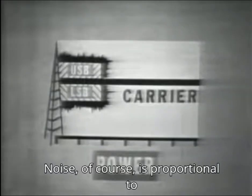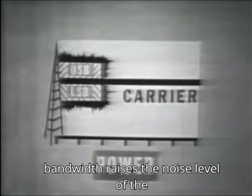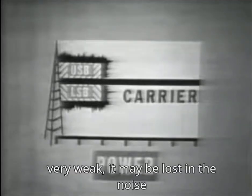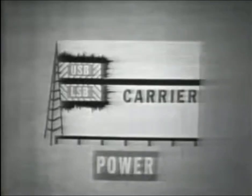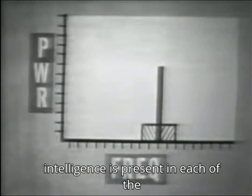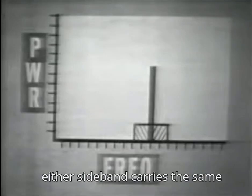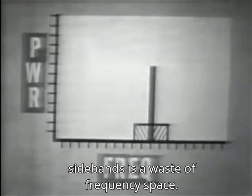Noise, of course, is proportional to bandwidth. Thus, the wider bandwidth raises the noise level of the signal. If the signal is very weak, it may be lost in the noise and thus be totally unusable. Now, we have seen that identical intelligence is present in each of the sidebands. Since either sideband carries the same intelligence, transmitting both sidebands is a waste of frequency space.